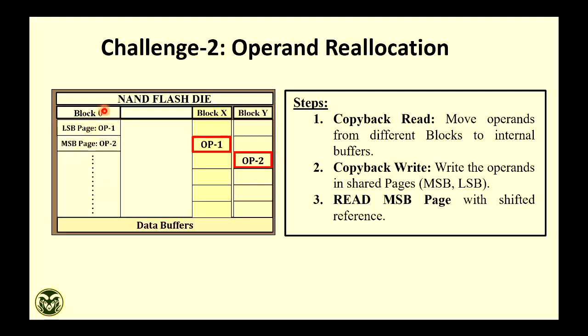Similarly, we will reserve, say, block 0. This is our computing block. Now from the data blocks, we will fetch the operand using this same copy operation. And it looks like NAND already has this copy operation. From the array, the data will come to the buffer, and from the buffer it will go to this logical page. That is already a commodity command in NAND. So data movement inside the NAND without taking data out is already there. We did this copy back operation.